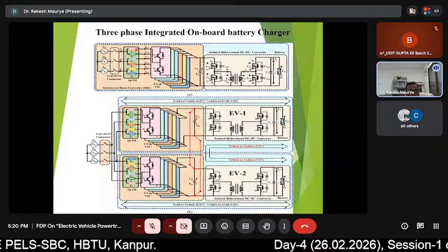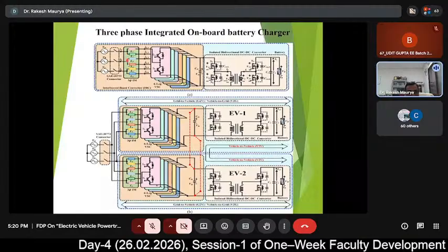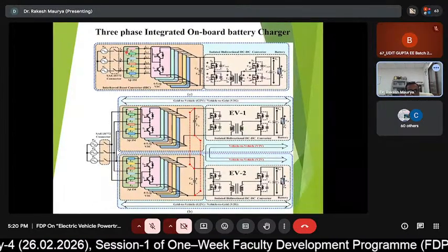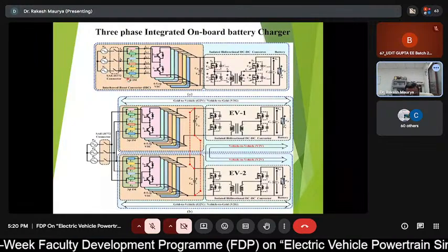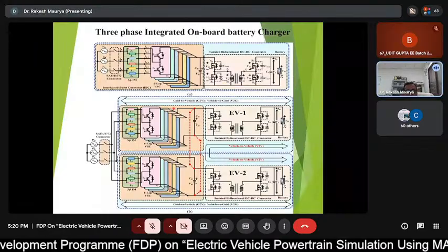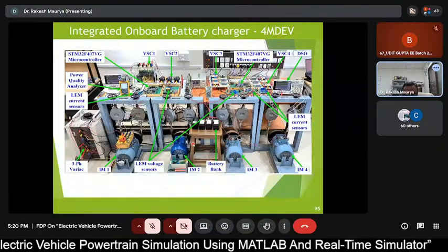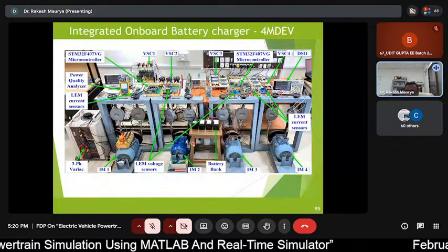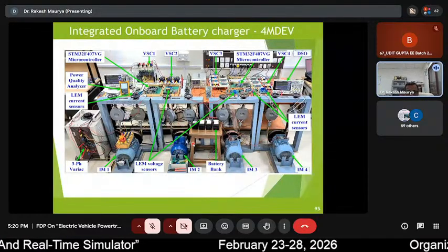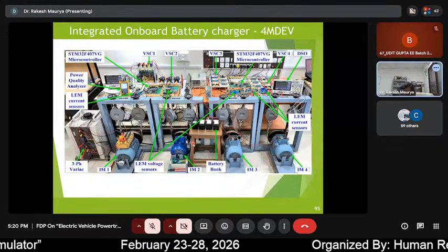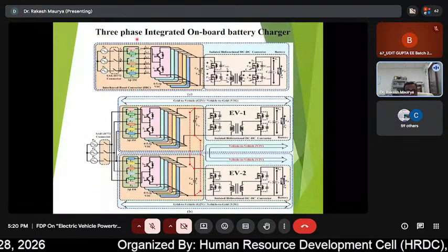Here we have customized the motor, because for each phase, their midpoint we have taken out. This is purposely done so that when you are operating with the three-phase supply, the rotating torque should not be produced. Otherwise, while charging, you have to lift your vehicle from the ground so that it should not run. So you need to make a change in this motor vehicle.